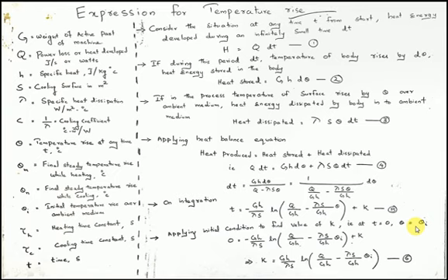Then next you started the machine in the very next minute. So while starting the machine in the very next minute, that is the 31st minute, at that instant the surface temperature is not same as that of the ambient medium. It will be something very much close to 40 degrees, because it might have started reducing gradually from 40 degrees in that 1 minute. So when you try to start the machine at the 31st minute, the initial temperature rise is 9 degrees Celsius over the ambient medium.